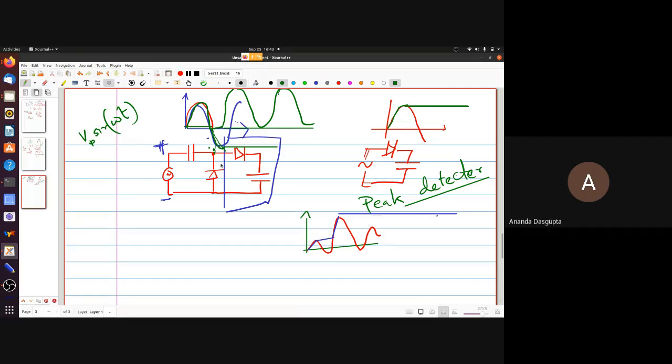In pulse shaping, its usage is that this is actually used really as a peak-to-peak detector, because a general input may be asymmetric, may be something like this. You may have a small value up here and a large value down here. But the capacitor, of course, charges down until it reaches this voltage and holds that. So the whole output gets pushed up by that amount.